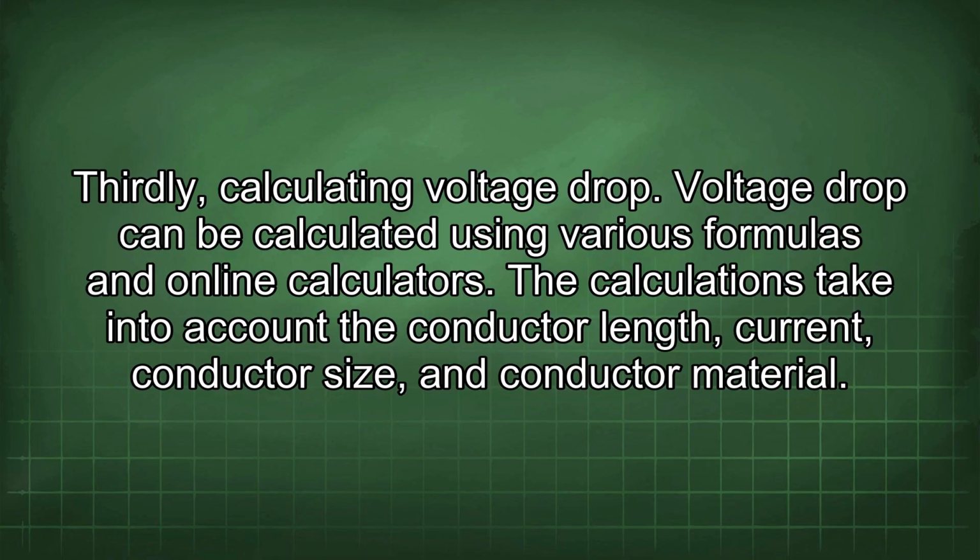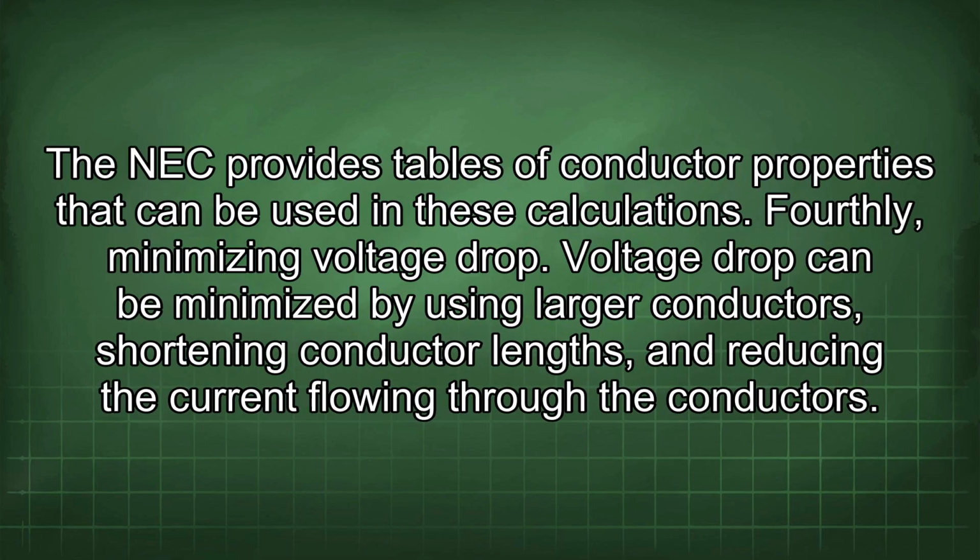Thirdly, calculating voltage drop. Voltage drop can be calculated using various formulas and online calculators. The calculations take into account the conductor length, current, conductor size, and conductor material. The NEC provides tables of conductor properties that can be used in these calculations.